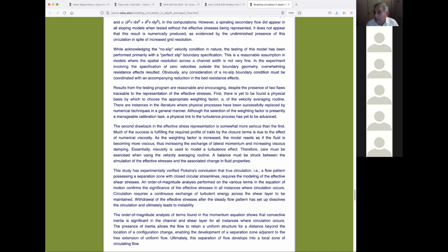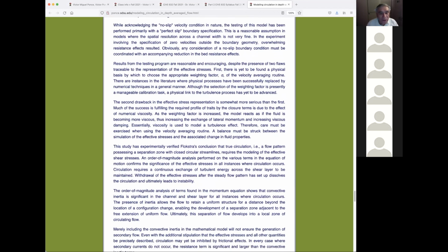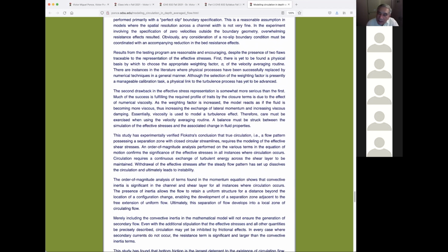We showed that already. It's like you took a whole bunch of aspirins, like 10. I don't know how many aspirins you have to take to kill yourself, but 10 aspirins is a lot, and then you will go around like a zombie. You've been doped by the aspirin. The same thing in here. If you increase the alpha high enough, like 0.7, 0.8, it will start doping, meaning it will start obliterating the answer. That's exactly the way it happens. That's just the way it is. It's in the nature of the numerical scheme.